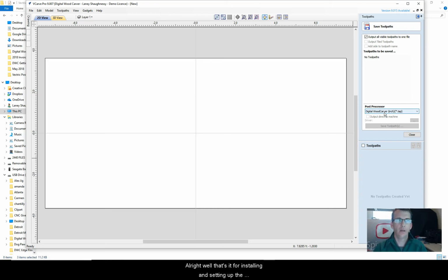Alright, that's it for installing and setting up the Vectric VCarve Pro desktop or Aspire software. Very simple. Stick in the flash drive and install your program as well as the clip art and run through the wizards. Be sure to go in and update your post processor files if you have an earlier version than 9.5, as well as update the speeds and feeds in your router bit, your feed rate and plunge rate, in your tool database. Be sure to set your clock appropriately.